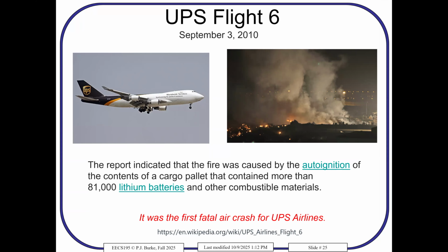If it's puffy, I would recommend you dispose of it, because that means that air has formed on the inside of it. It's mechanically less stable, and I would just dispose of it. And it also doesn't last a long time. But if you have a 6-year-old battery that's been charged at storage charge, and it hasn't been abused by being at a high temperature, then it probably still is okay to use.